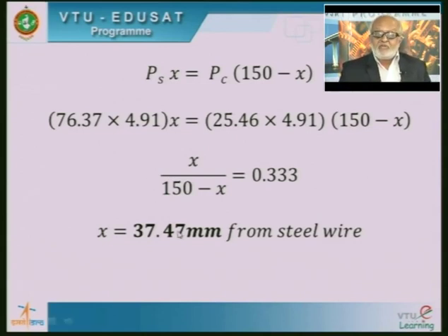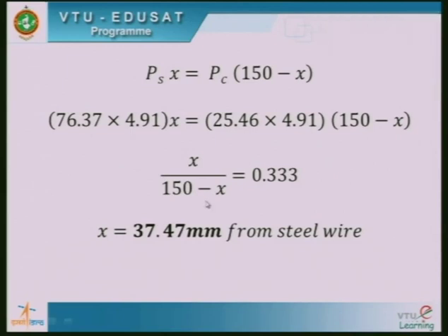Suppose you suspend this load at the center, then what would have happened? Obviously, the moments would not have been balanced out. The load carried by steel and load carried by copper, multiplied by these lever arm distances, will change, as a result of which an unbalanced moment will be there, and because of that, instead of remaining horizontal, your bar may rotate like this or it may rotate like this.